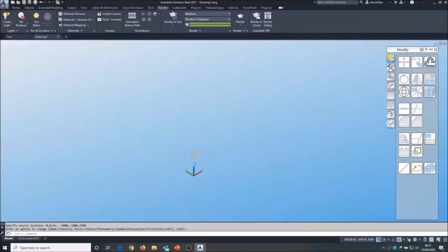Then I'm going to use the AutoCAD 3D array. Pick that light source and put in a pattern of those to cover an area just for starters. So a few in each direction, a couple of levels, put in some spacing, a few meters apart. There you go, there's some lights in there. That's enough to get me started. Cover a small model, wouldn't it?